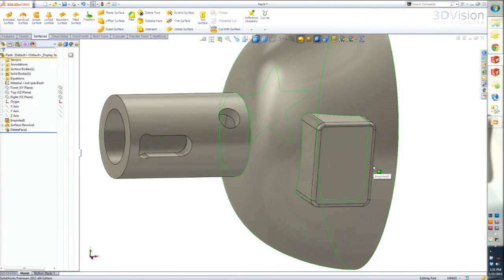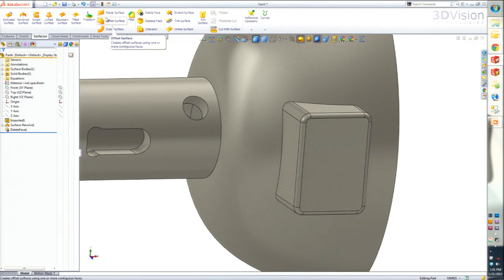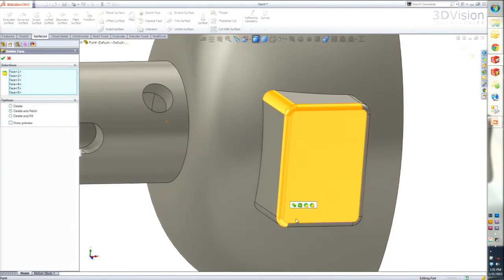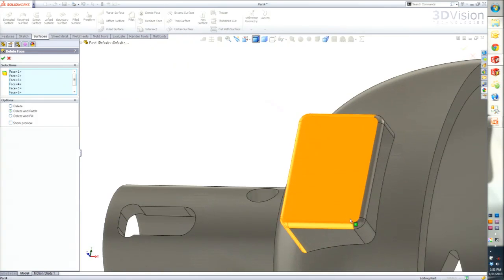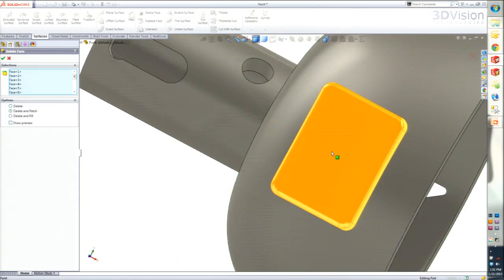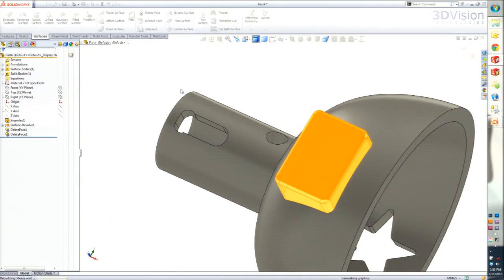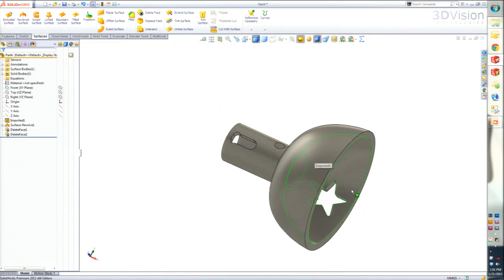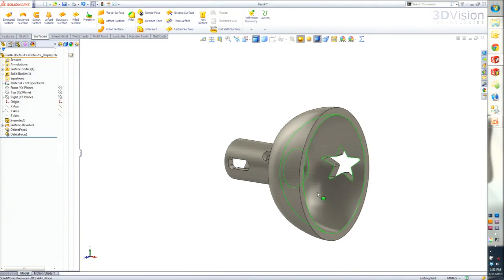as well. Pretty simple. What if I wanted to get rid of all of that entire feature? I could run that command one more time, or just edit the previous one. But let me go ahead and select all of these faces. Let's see which, oh, that option's a better one. There we go. So selecting all those, delete and patch, and that whole chunk of material is gone as well. So you can see how you could use this very easily to simplify your geometry. Okay?